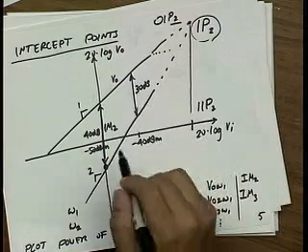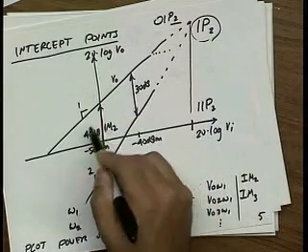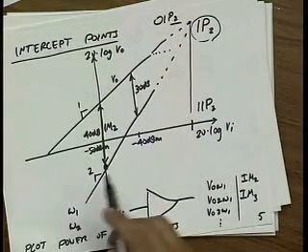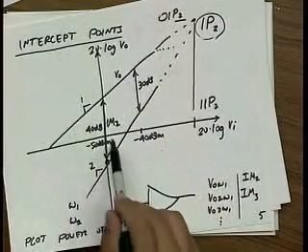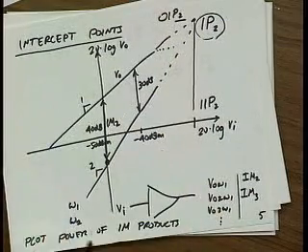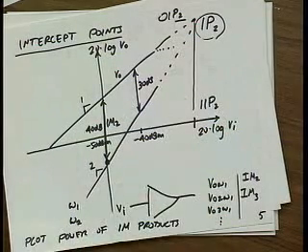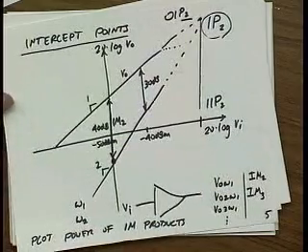What's cool is I can do a measurement at really low power. I just need a couple of points here, and I can extrapolate the IP2 point. In fact, it's even better than that. If I go to really low powers, then I know these slopes ideally should be 2 to 1 and 1 to 1. So from just one point of IM measurements, I can extrapolate the IP2 point for an amplifier. Questions?